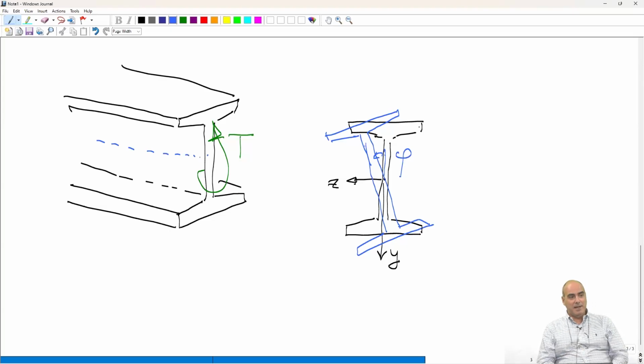But in the beam, there is one cross-section which can never warp. In that beam, which one is it? The midspan. Because the midspan is a symmetry cross-section, and actually that cross-section doesn't know whether to warp leftward or rightward. So in this uncertainty, it will not warp.